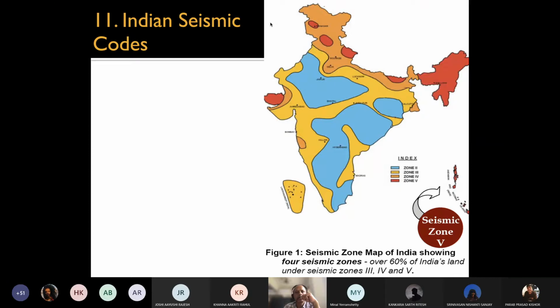So Bombay itself, there is a fault line very near to the city, and so each region, each space, though it might be in a larger region, there's a specific locational understanding of geomorphology that has to be understood to arrive at the vulnerability of that region, rather than taking for granted the vulnerability as a larger generic thing. Specific instances about the soil typography or geohydrological understanding of each site should be well understood. The region should be well understood before you can understand what exactly will be the vulnerability in terms of seismic.